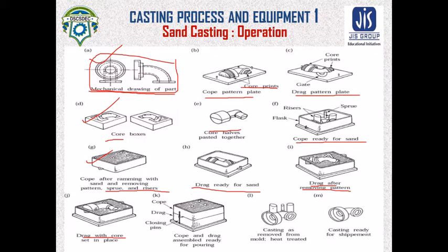Like we can have the casting as per the design, but along with the gating system and risers and vents, etc. So further processing is needed to remove all this material. Further processing is needed to remove riser, vents and sprue and other gating system elements. So that is done, and